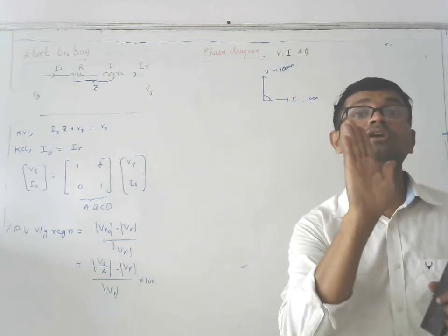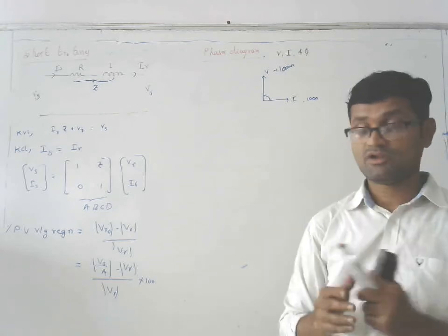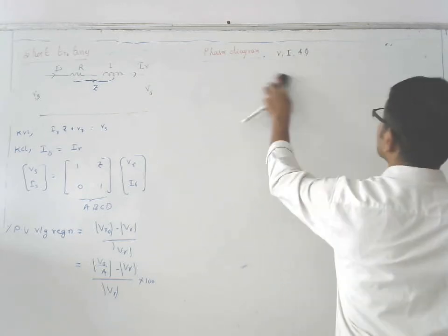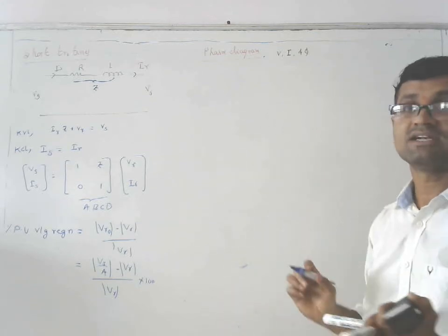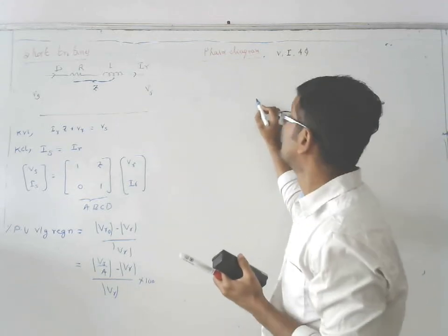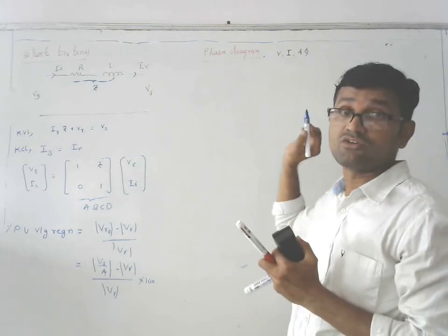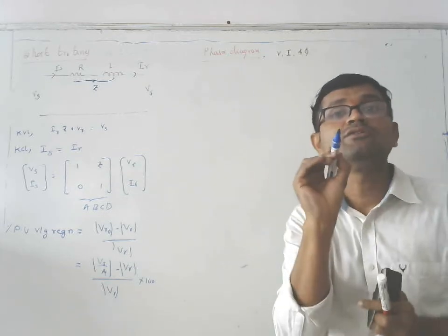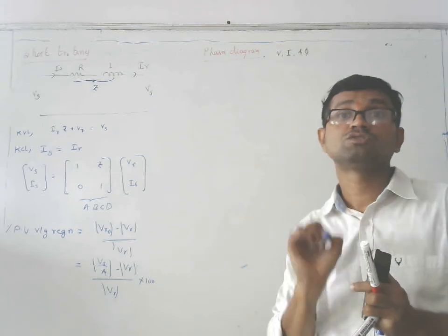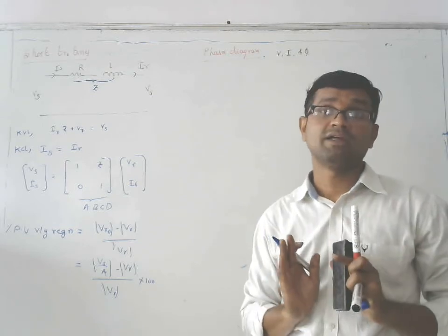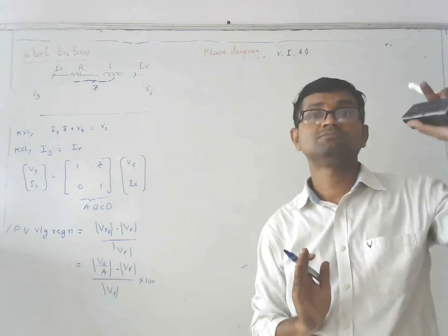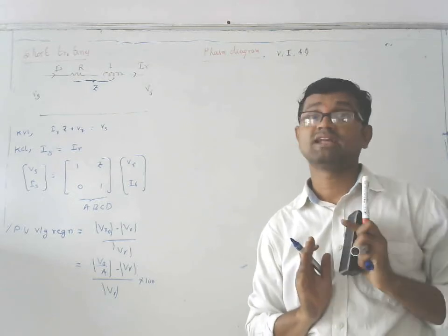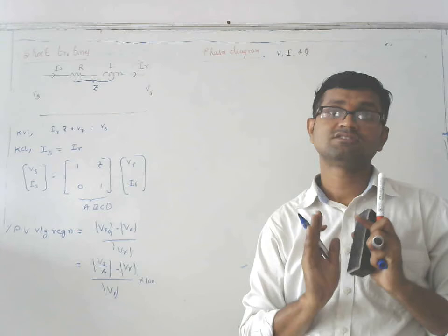Now with this analysis, first how to design the phasor diagram or vector diagram? For all vectors we need to define magnitude and direction. If we define a voltage source, the voltage magnitude represents how much voltage, 200 volts or 300 volts. Similarly, polarities, which is positive or negative, represent direction. Similarly for currents and also for fluxes, we define magnitude and direction. That's why voltage, currents and fluxes are called vectors.